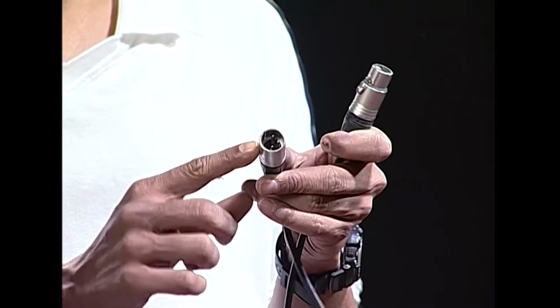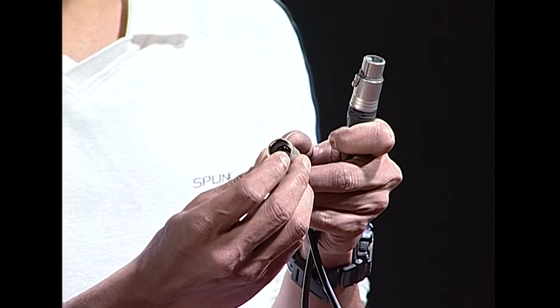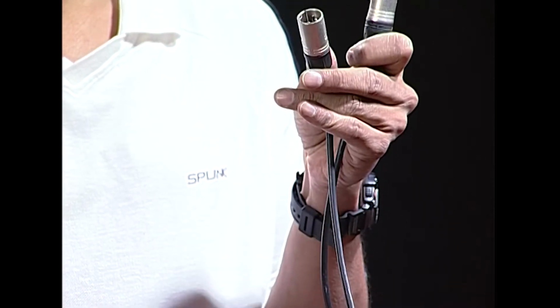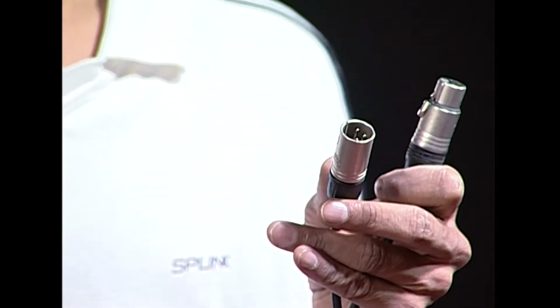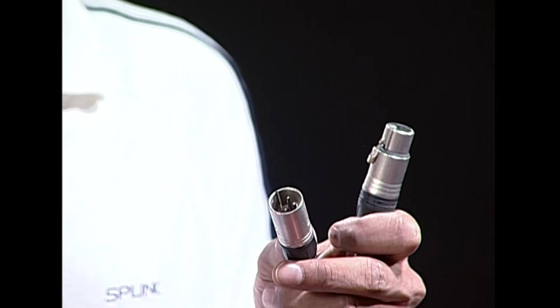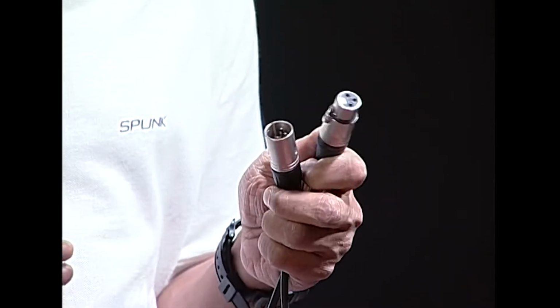This type of connector is called an XLR connector. You can make out that there are three wires running inside the connector. One wire is carrying the signal, so that's the positive wire. One wire is carrying the negative signal, and the third wire is basically grounding any noise which can be seeping inside this cable or inside the microphone. Any noise can be generated from any high frequency, for example noises generated from tube light chokes or from other electrical lines running along.